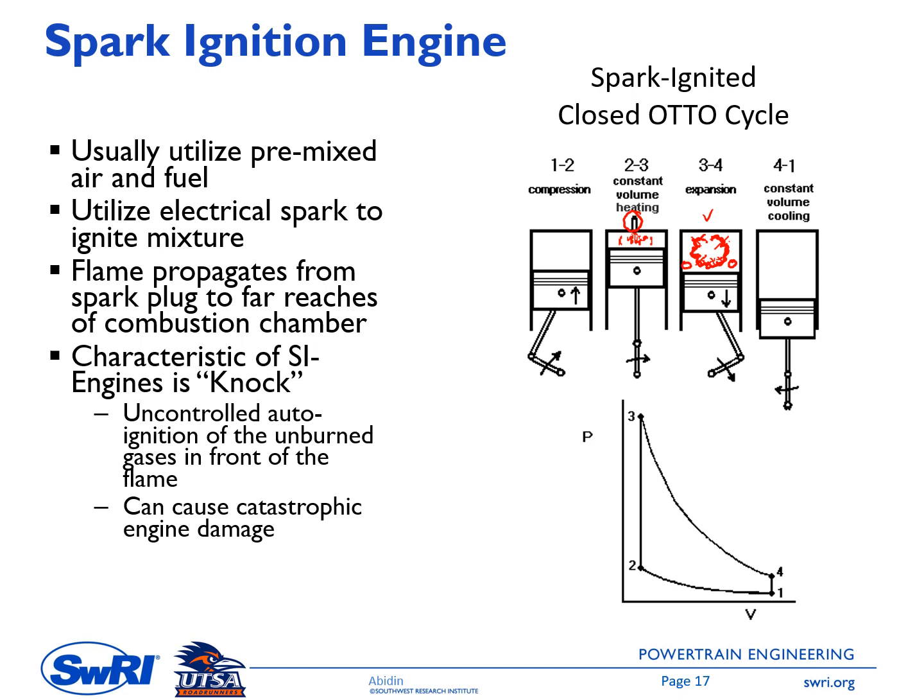When that happens, it's bad, because it can damage engine components, especially the piston. Knock here is an uncontrolled auto-ignition of the unburned gas in front of the flame, and once again it can cause catastrophic engine damage. So we need to avoid this knocking process.